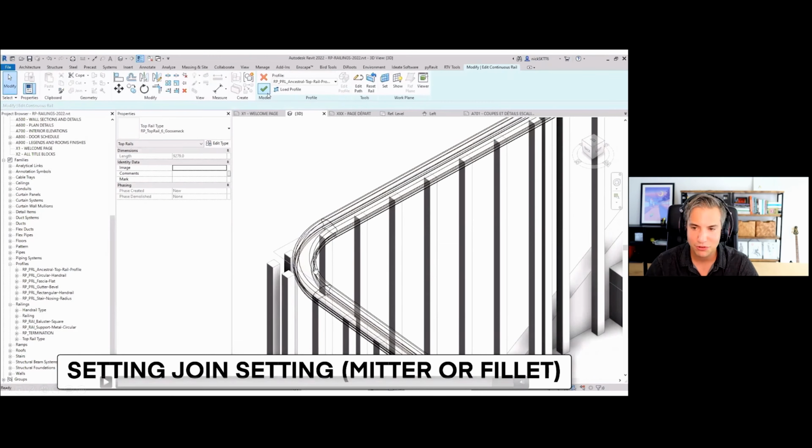So you can see we have the radius we want, but once again, you can see there are some problems with the balusters. So for horizontal transitions, this option can be a little tricky with the balusters. So that's why in this case, you might use the actual railing path to create a little curve to make sure that the balusters will also follow along with it.